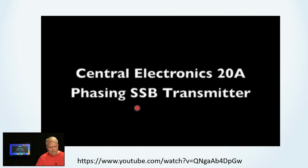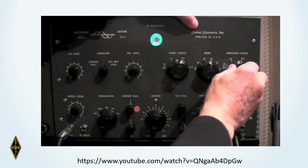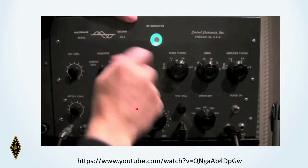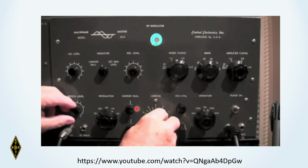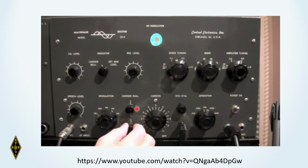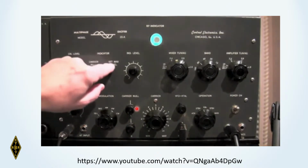Oh, and before I do that, though, let me go ahead and turn on original sound so you can hear all the beeps and boops. And this is how I tuned it up. You'll hear the receiver. We select the band, 80 meters, 75 meters. Then we're going to put this in the carrier null. Now watch. We're going to take those two out of phase, and away went the carrier. There's our carrier null. You can hear in the receiver when I had it up, but very carefully, I'm nulling those two signals, just like with those two microphones. And when we get it all correct, a little eye up on top will tell us, but then you can also listen in the receiver.